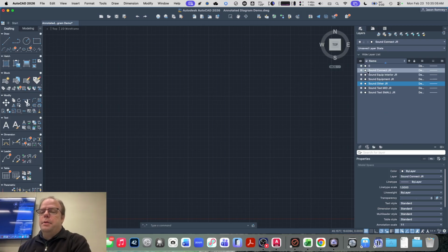And then I want to make some colors for these things, because the colors help you know what layer you've drawn it on. That way you'll know if you've got it in the right place or not, because the layers only help you if you draw the right lines on the right layers. If you draw them on a different layer, then the layers don't help you. So having each layer have a different color will help you know when you've drawn it on the right layer or not.